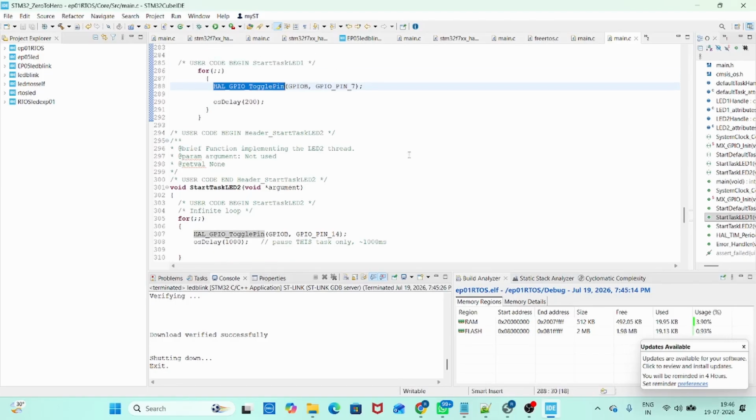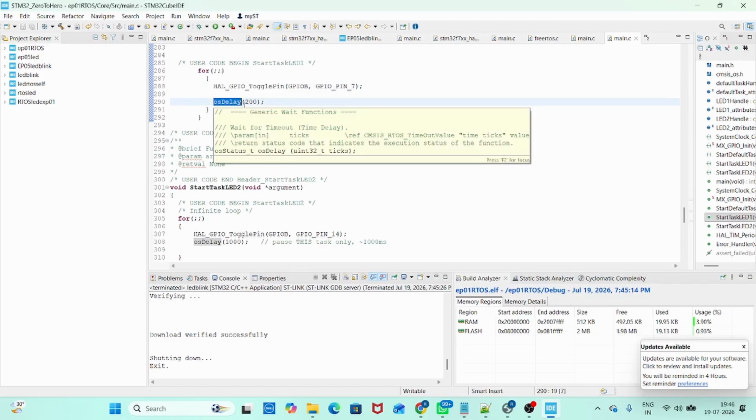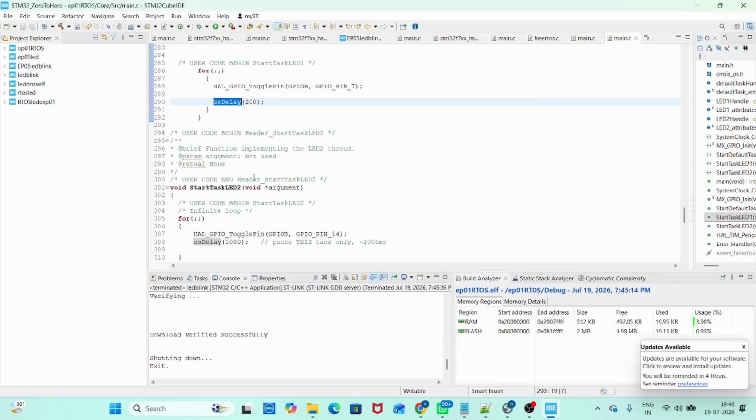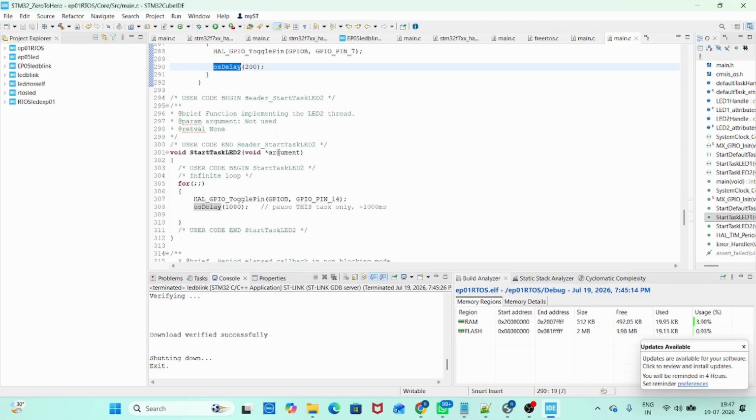Right now, what happens in this program is when this task starts toggling the LED, immediately after this it will go into sleep mode for some time, say 200 millisecond, and during this interval the CPU can do another task. Okay, so this RTOS will take the second ready task which is to be executed by the operating system, right? And this is how these two tasks continuously share the CPU and execute in a sequence one by one.